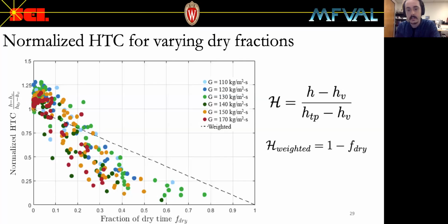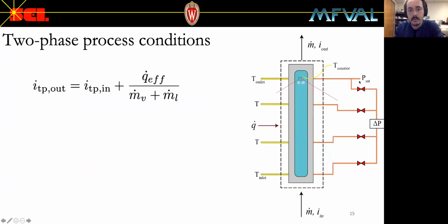Yeah, the heat loss is so. The dominating uncertainty of the heat input into the refrigerant is this pressure transducer here. So this absolute pressure transducer here is the dominating uncertainty for the heat input into the refrigerant. So the refrigerant properties are calculated using the saturation temperature and pressure, and that's where the uncertainty comes from here. But as far as the uncertainty on the heater input into the wall, even though it's still 99% going into the fluid, that's still the biggest uncertainty there. Yep. All right.